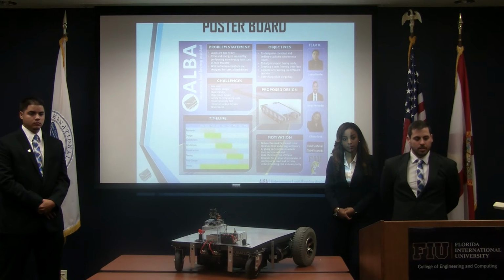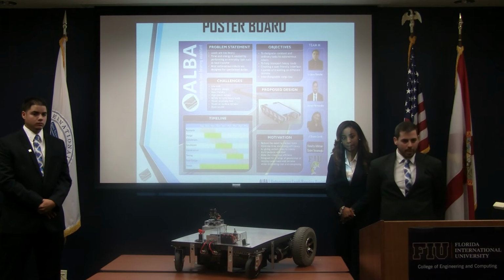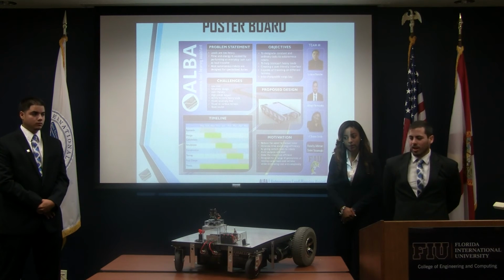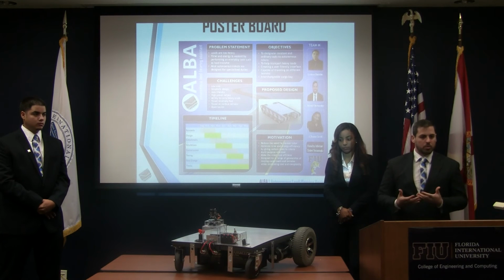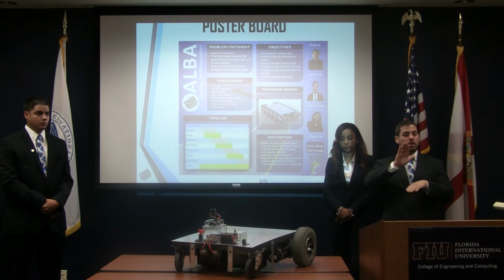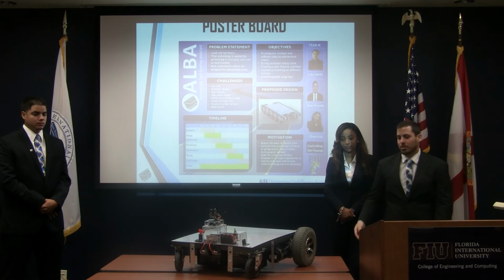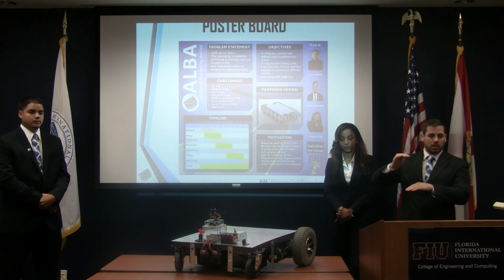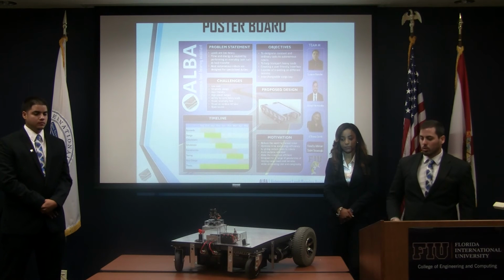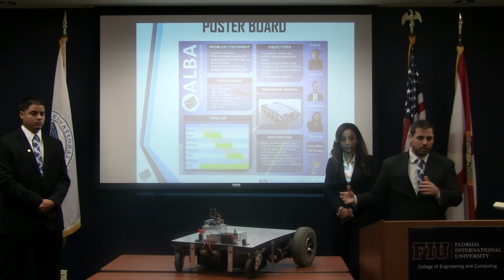Okay, I know this is a prototype, but what would you implement to protect your components? I see that the camera is exposed. At first, we were going to put all the electronics on the bottom, but we needed the camera to be a lot higher because we had issues at the beginning. It was sitting so low that it was really hard to pick up the target, like somebody wearing a shirt, especially someone taller. So we put all the electronics on top, with a little base for the camera. In future work we can make guardrails on the top so nothing can slide around and move.